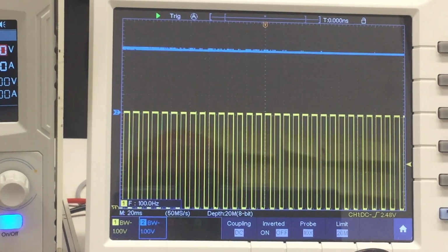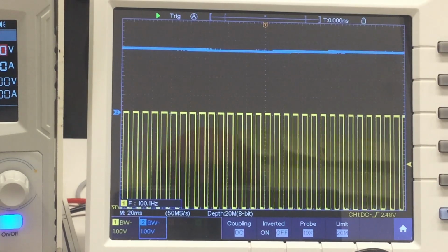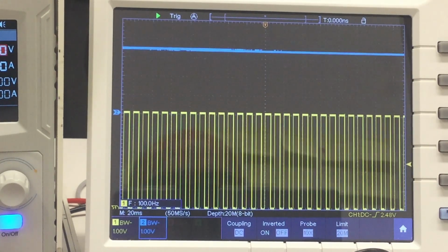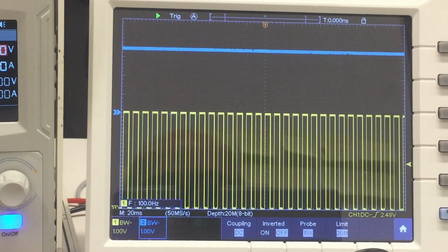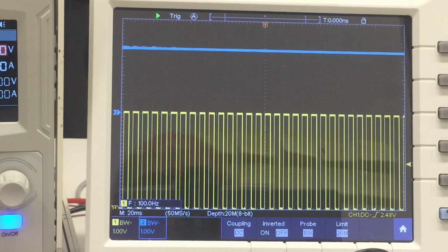But what we have here, the yellow trace, of course, the frequency out at exactly 100 Hertz, which is incidentally the second harmonic of our mains AC 50 Hertz here in Germany. And above it, our V out, our signal level indicator, is not quite at 5 volts. It would be at 5 volts when it's at the very top. So that's the radar with no activity.